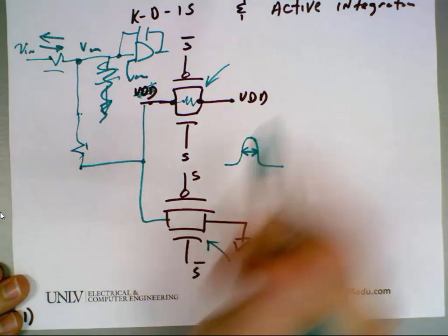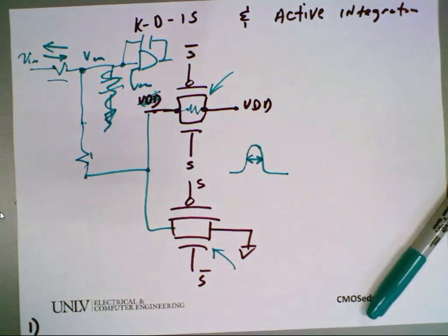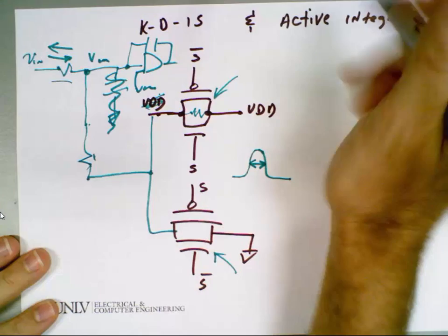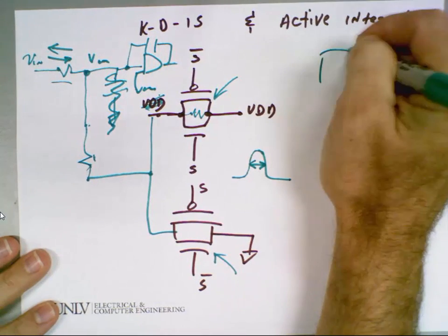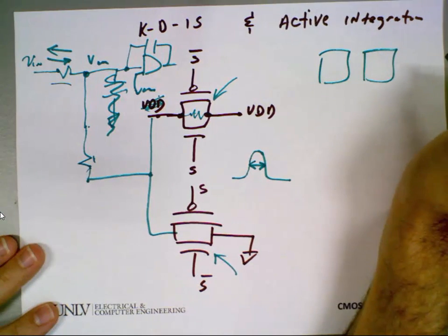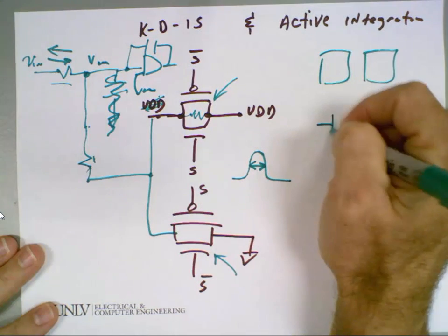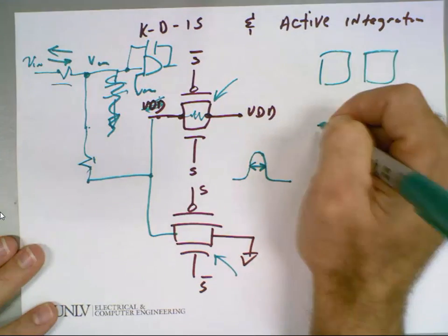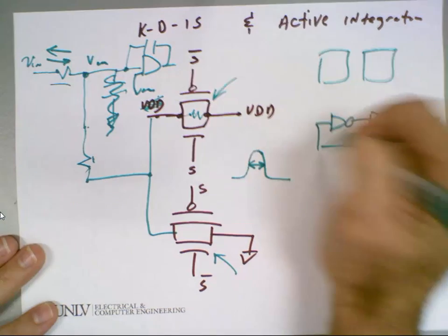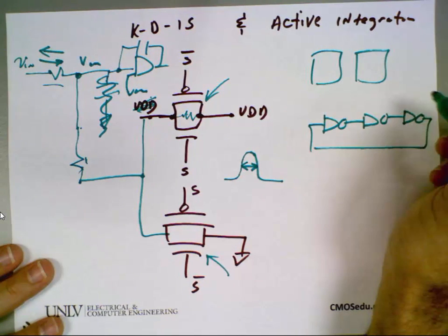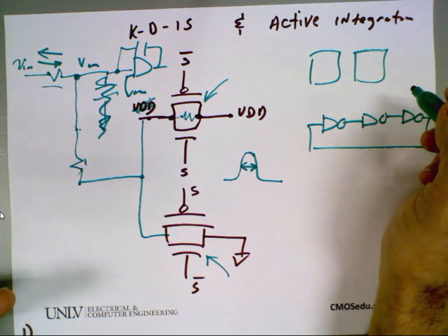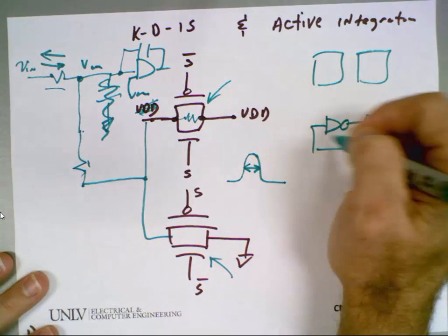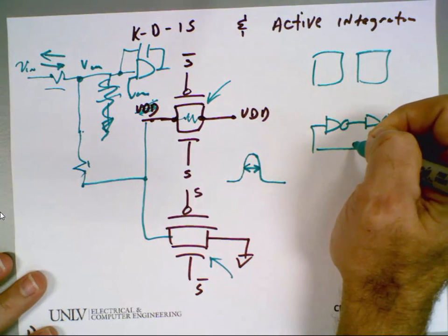If you look at the clock generator that I built, I put in stages so that I could have an even number of stages. But if I have a ring oscillator like this with an odd number of stages, let's just do a 3-stage, you're not going to have 8 evenly spaced edges. If you did 7 or 9, you don't have 8 evenly spaced edges.